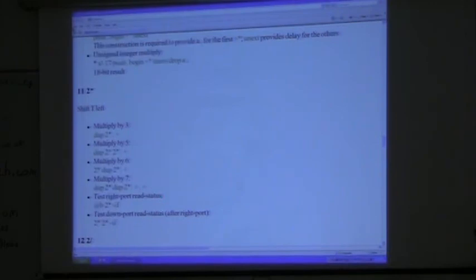If you want, you can look at your neighbor ports and see if they're reading from you or writing to you. And you do that by reading the port with a fetch B and then doing 2 stars to shift the bit you want into the signed bit position so you can use a minus if on it. Read IOCS, not the port. If you read the port, you go to sleep. IOCS is where the status of your neighbor ports is found. Quite right. And likewise, typically the port statuses are 2 bits apart, so you need 2 star in between things. If you set it up really carefully, 2 star minus if is all in the same word and doesn't cost you much.